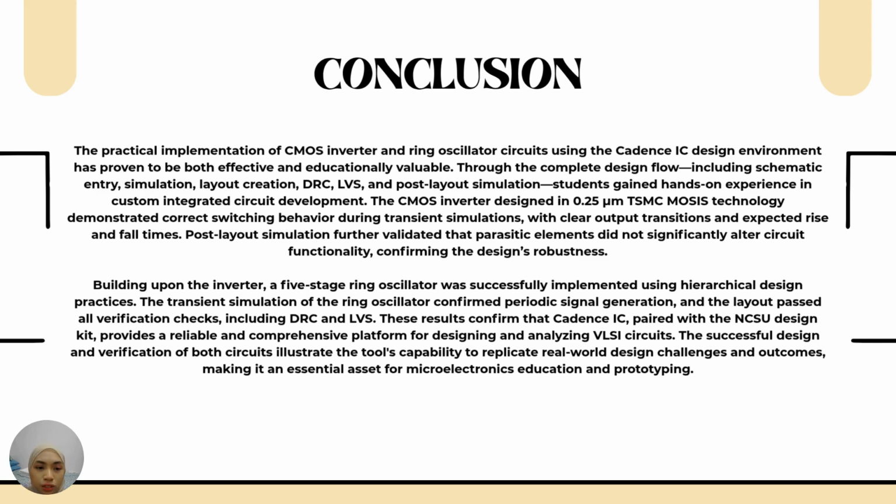The practical implementation of CMOS inverter and ring oscillator circuit using the Cadence IC design environment has proven to be both effective and educationally valuable. Through the complete design flow, including schematic entry, simulation, layout creation, DRC, LVS, and post-layout simulation, students gain hands-on experience in custom integrated circuit development.